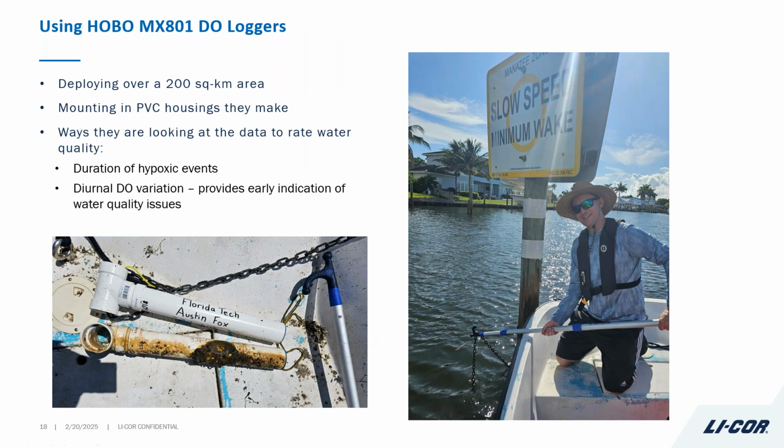So again, deploying them over a large 200 square kilometer area, and you can see the PVC housings that he's making. He's got a kind of clever approach here by putting a T pipe on the end of it, and he uses that to run a chain through, and that chain is what he uses to attach the PVC housing to structures so that he can go and retrieve the data. Here he's attaching it to a post for a sign in the estuary. So I thought that was a pretty good way of mounting them.